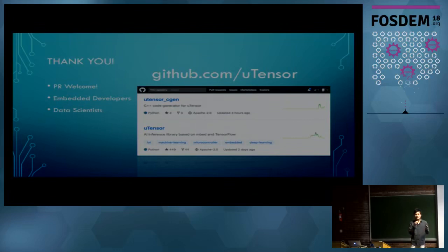When you do the quantization using TensorFlow's tools, you will insert a bunch of quantization operators in your original graph. And what we did here is also port those quantization operators to MicroTensor. That's why they are compatible. But yes, training is done in floating point, and there are tools for us to convert everything from floating point to fixed point to run on the MCU.